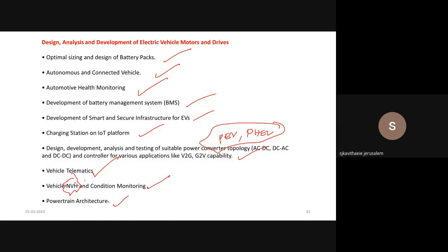Ashish sir has asked about various torque control methods. See, as far as torque is concerned, torque control is current control. If you want to control the torque, the immediate operating variable which controls torque is the current. The current has to be controlled. To control the current, you can prefer the PWM technique. Whether it is an induction machine or some other special electrical machine, certainly in an electric vehicle, control is operated by means of a front end converter. It has many power electronic switches which are triggered at some frequency.